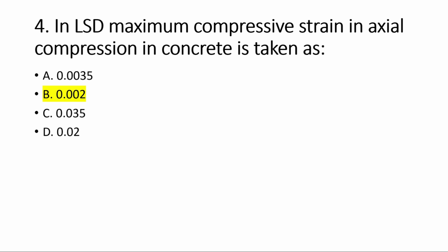Option B is correct. While for the maximum compressive strain in flexural compression, we know the maximum compressive strain is taken as 0.0035, according to IS 456:2000.